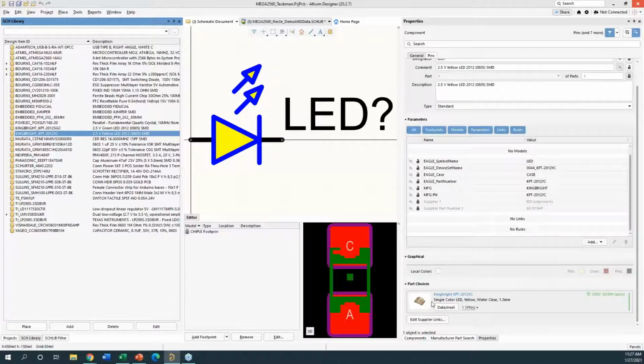When it came to parametric information, the only thing I demanded that they be consistent on was manufacturer name and manufacturer part number. And later on, if they had a value, they could add a value in there too, so we could display it. Those are the three things that I demanded that they put in as rock solid parameters.